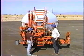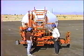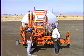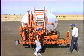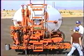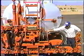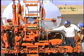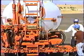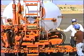Okay, in order to minimize the coking, we're going to circulate the material from the back of the tank to the front of the tank. Starting out over here, you come around here, you can see the main tank valve is right on the back of the tank. It's directly connected to the tank so that it heats up with the material in the tank.